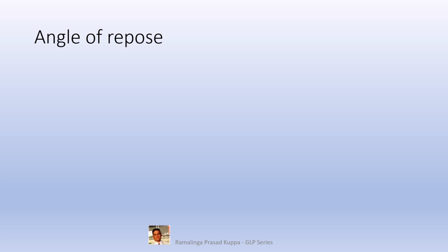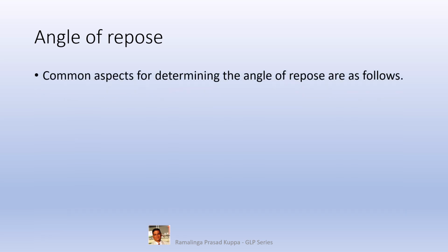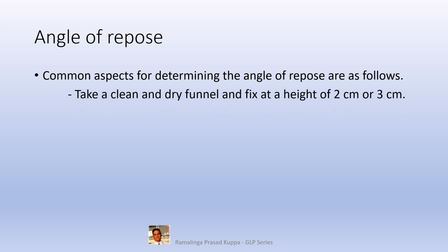Angle of repose. Let us consider the most frequently used test, angle of repose. Common aspects for determining the angle of repose are as follows. Take a clean and dry funnel and fix at a height of 2 centimeters or 3 centimeters. This is important. The funnel should be totally clean and dry. It should be free from oily or sticky stuff. Otherwise, the powder is likely to stick to the sides of the funnel.